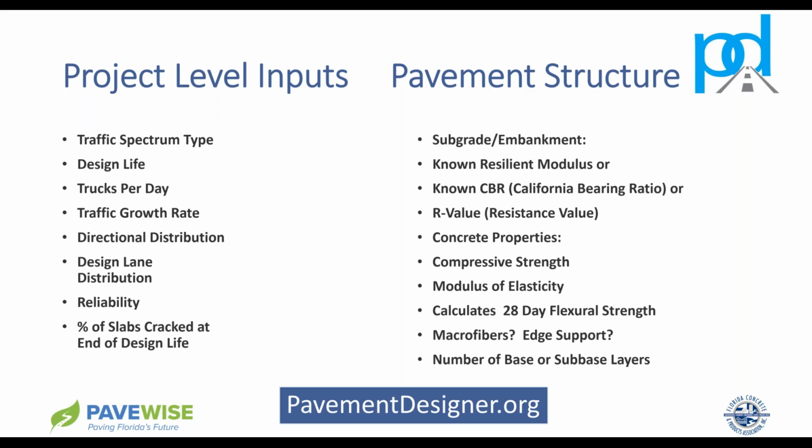Reliability is a number between 50 and 99. How good do you want your design? Do you want it 99% of the time? If it's going to last 20 years for the DOT, then that's what you pick. If you want 95, you pick 95.